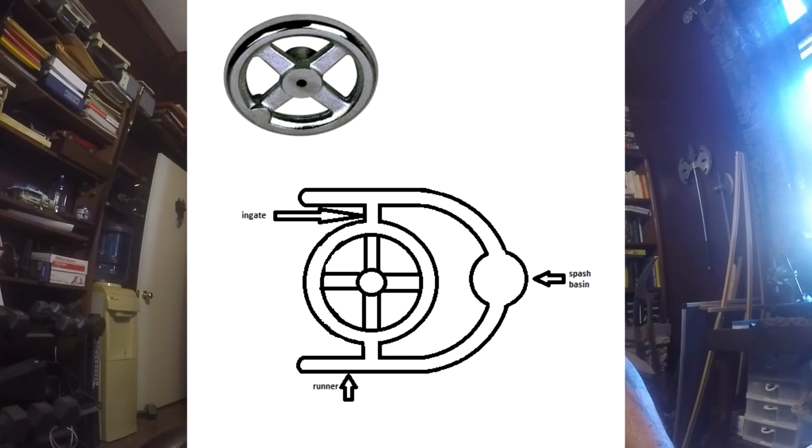After the metal stopped, those spokes would solidify, and the bottom of that central hub would start to solidify, and that riser, because it was the last bit of it and was the hottest metal, would solidify last, feeding that central hub. Okay, now that's your basic hand wheel.